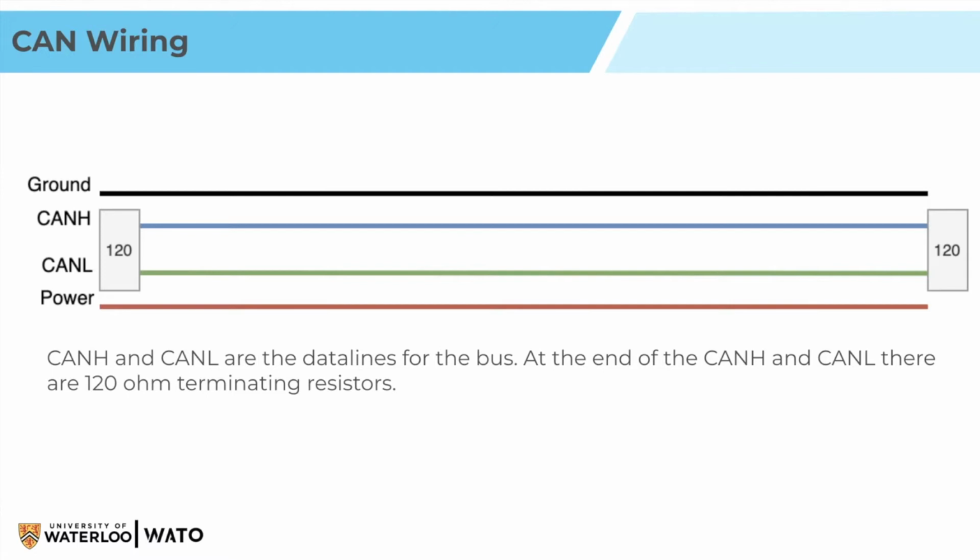If a voltage exceeds that voltage threshold, then it's a logic 1. If not, it's a logic 0. So having these resistors as a pull up or pull down, a pull up resistor will take a voltage on that line and pull it up to a logic 1. A pull down resistor is going to pull that voltage that you have on the bus down to a logic 0. So these terminating resistors will help regulate to make sure that the voltages are correct and that you're getting that voltage threshold that you want.